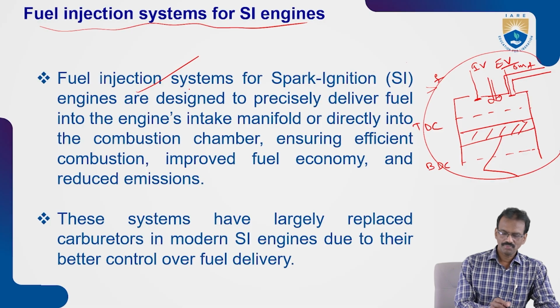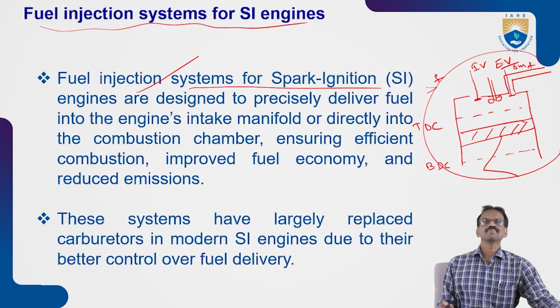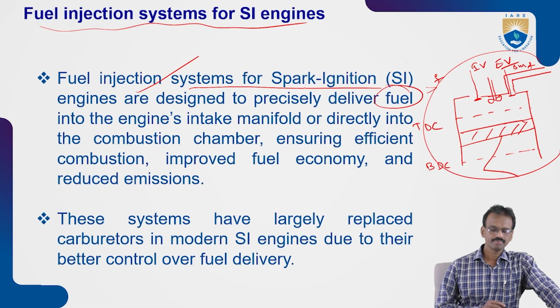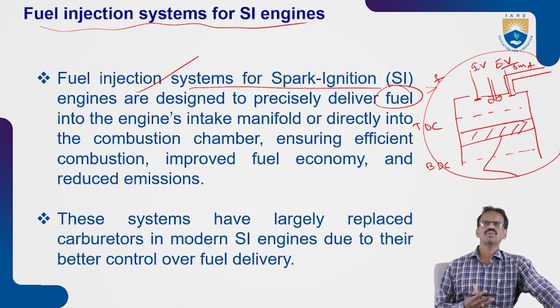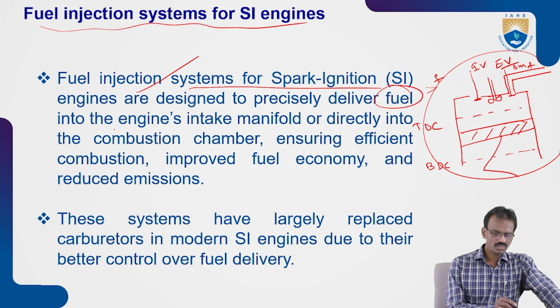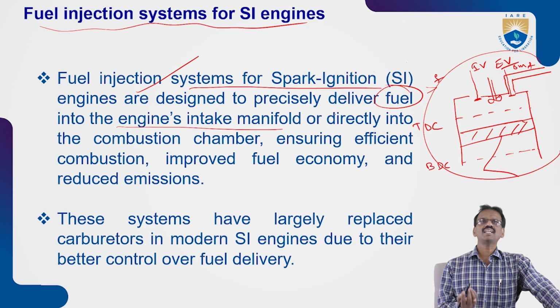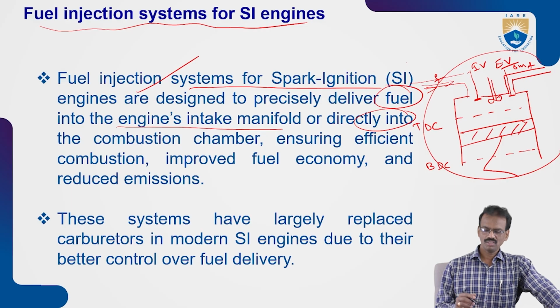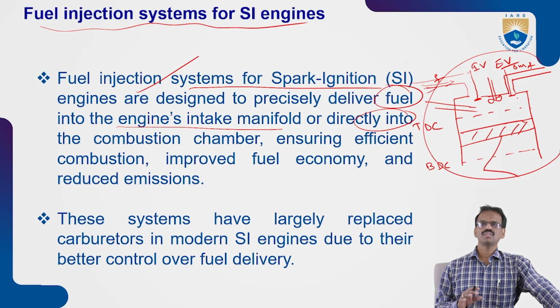Fuel injection systems for spark ignition engines are designed to precisely deliver the required amount of fuel into the engine's intake manifold or directly into the combustion chamber. There are two methods: through the inlet manifold we can supply the air-fuel charge into the cylinder, otherwise we can directly inject it into the cylinder.